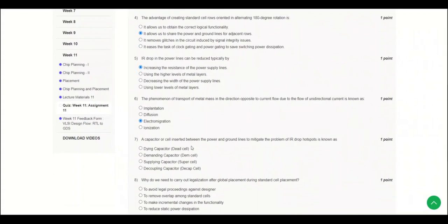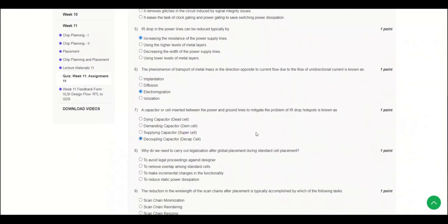This is how the wire length estimate can be made for a given net. This is a very simple method, and the half perimeter wire length method is the simplest and also widely used. There are more sophisticated methods of finding more accurate wire length estimates.